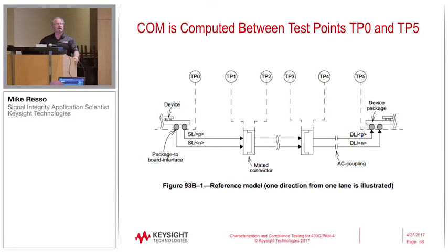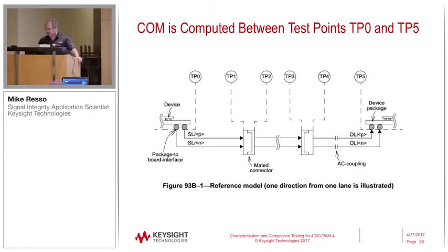144, right? So a 12-port S parameter is a 12 by 12. A 4-port S parameter measurement has 16 elements, right? Differential in, differential out, common in, common out, and then quadrants 2 and 3 are your mixed mode S parameters, okay?